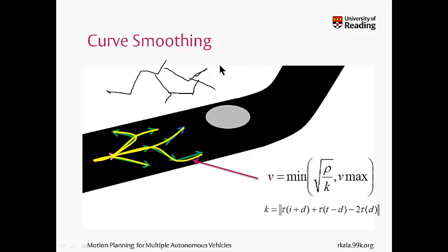It is exactly the same RRT. What we've done is that after every node, I use all these points or the paths from the source. I find out the path and I simply pass them through these spline curves, which generates a smooth curve like this, and that is what I've overlaid. I've overlaid the smooth spline curves over the old RRT. So for the expansion, for extending, I'll be using the actual RRT which lies underneath. I'll be using the same discrete non-smooth RRT, but along with it, after every insertion, I'll use the spline curves to generate a smooth trajectory that smoothens the tree so formulated, and that's what has been shown by this yellow curve.